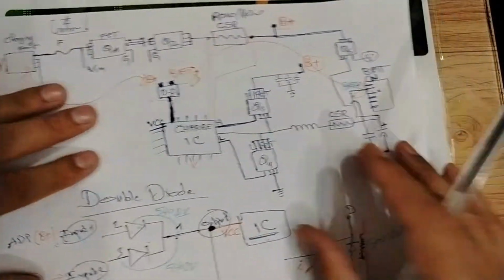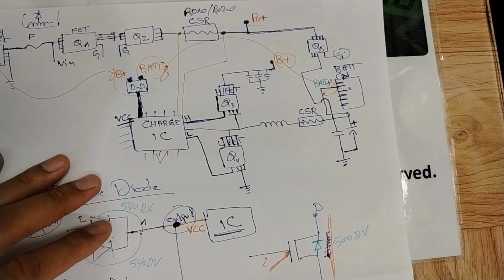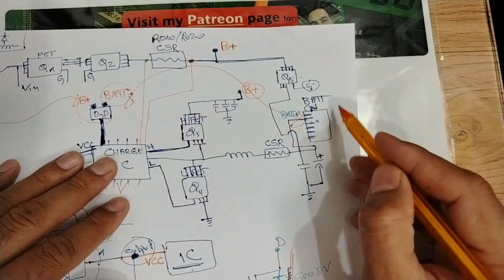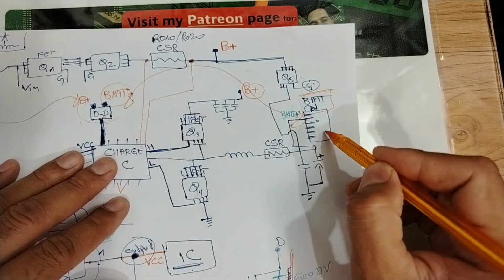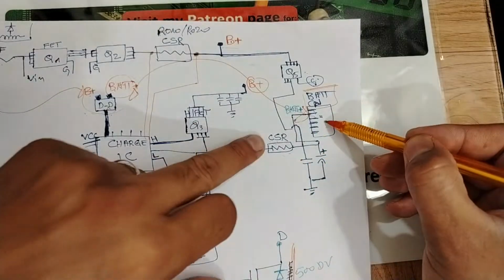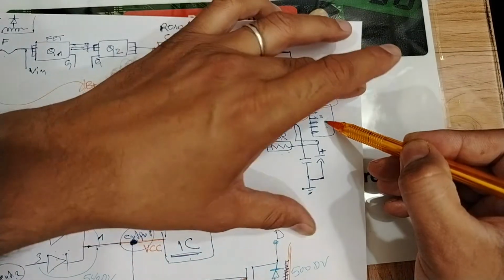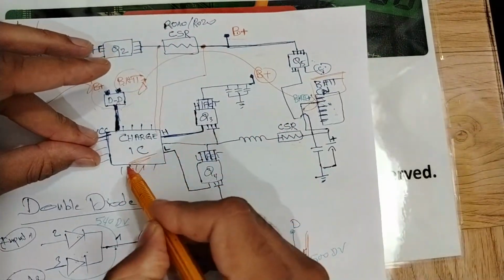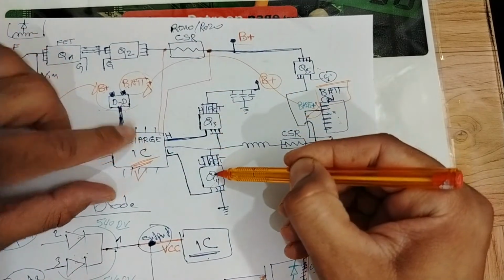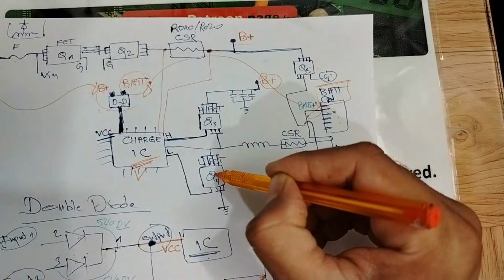Basically, my friend, if you understand this schematic, please attention, Alexander Luis. Here we have the battery connector. So you say that next to the battery connector you have a problem. What is exactly the component here that can fail? The charge IC, this one, my friend. It could be the two switches. Let's also use the motherboard in order to understand very clearly.